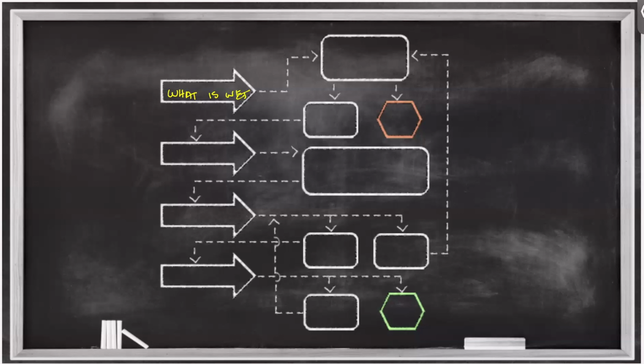In other words, it's not a floor that's wet. It's rebond cushion underneath a cut pile carpet, installed over a plywood subfloor. The plywood subfloor is over a joist system that is insulated, and there's a crawl space beneath. That's the level of detail we have to understand when we're defining what is wet, because that's going to directly impact all of our project variables, not the least of which is what we're going to talk about today, which is humidity control. Once we know what is wet, the next thing we have to talk about is what are we going to restore, right?